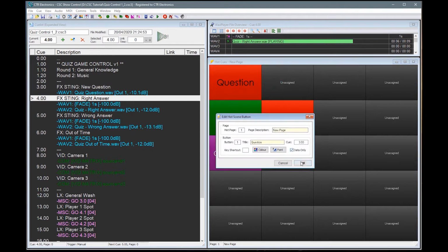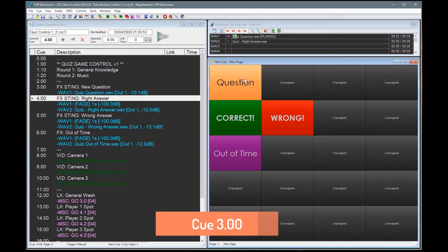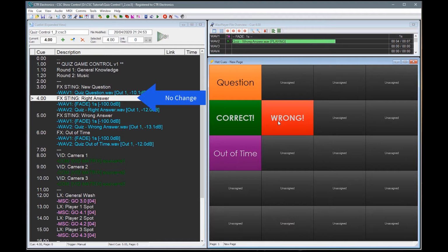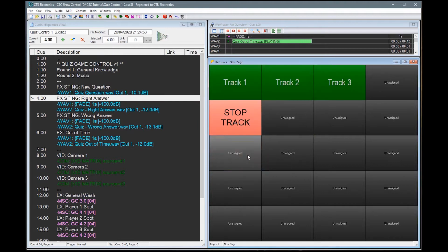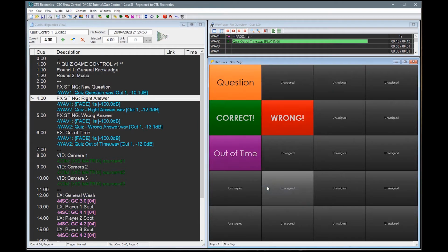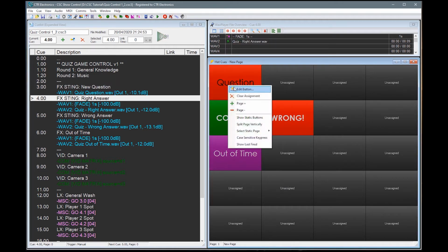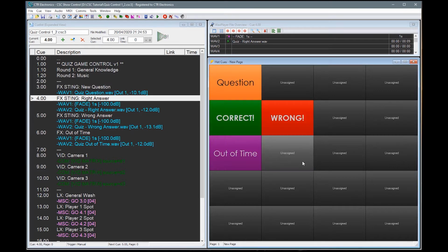Enabling the Data Only checkbox will prevent the cue list from changing position while still firing the data within the cue. Cues can now be fired instantly and independently of the main cue list. Of the 5 pages, the visible page can be chosen with the right-click context menu or, on a cue-by-cue basis, through the System Command window, covered later. Buttons can also be assigned a keyboard shortcut key to allow instant fire from the keyboard.